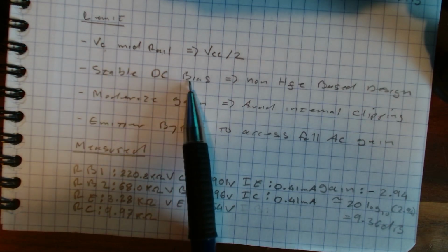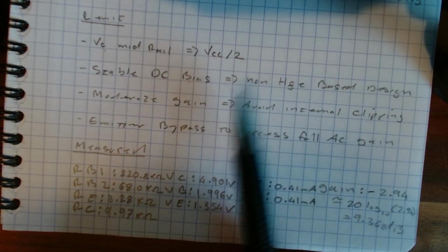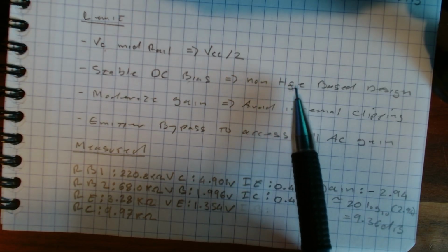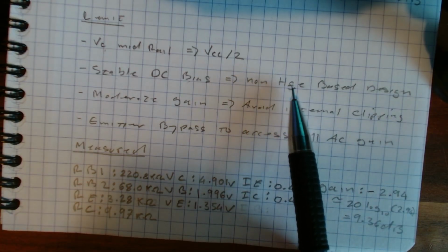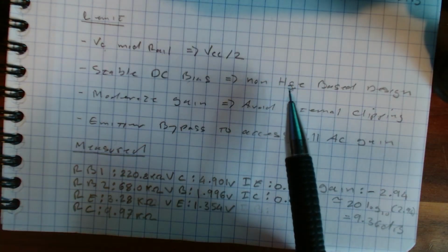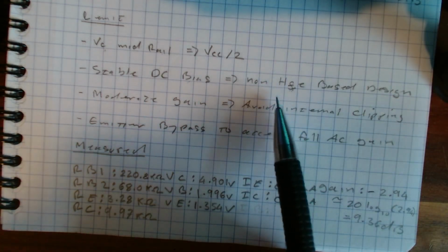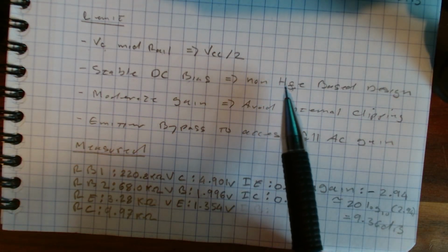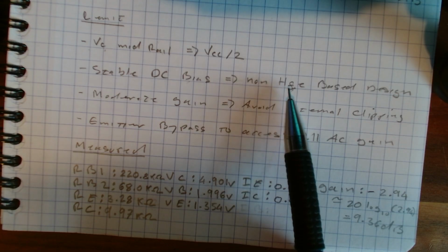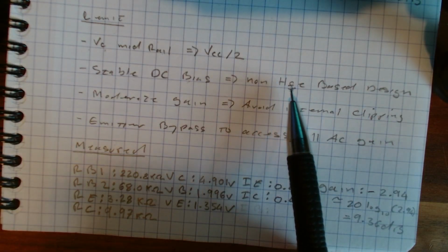We wanted stable DC, which essentially means that our output voltage wasn't flying around, and we're not basing our design on whatever our specific transistor's HFE is, which I think is the best way to design these things, because if you wanted to build 1 or 2 or 3 variations, you can work out mathematically how much gain you're going to get, as opposed to leaving it down to which part you got and playing what they call the silicon lottery.